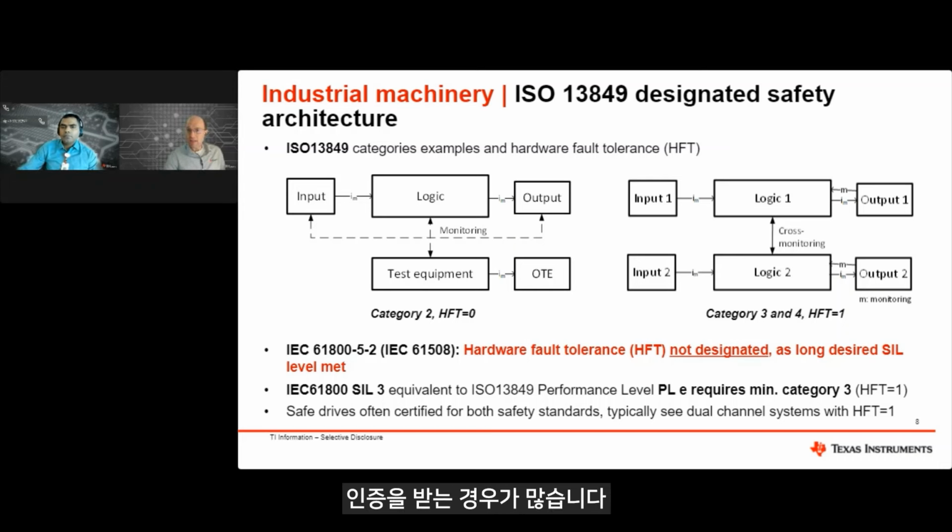Yes, Martin. In principle, the automotive functional safety standard, that is ISO 26262, is an adaptation of IEC 61508 and tuned for the automotive use cases. Hence, there are similarities in the processes and architectures required for functional safety in both the standards, and yet there are differences. As shown in the figure on the left side, ISO 26262 provides V model as a reference for product development and the automotive-specific risk-based approach for ASIL determination.